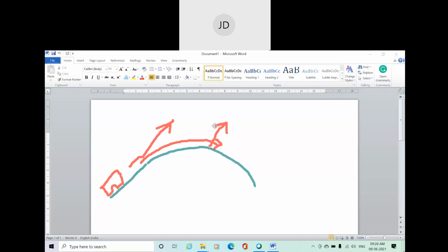To counteract the centrifugal force and safeguard the train against derailment, you have to provide a desirable super elevation. Also, we need to maintain a safe speed of the train.